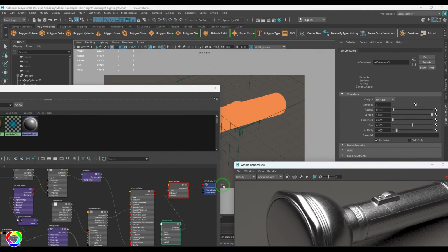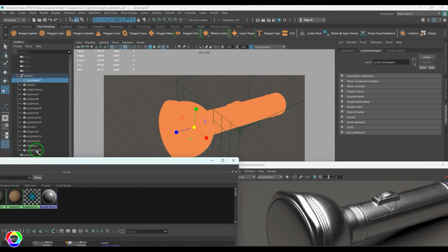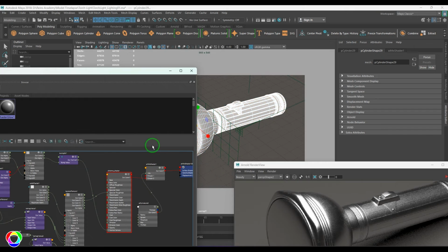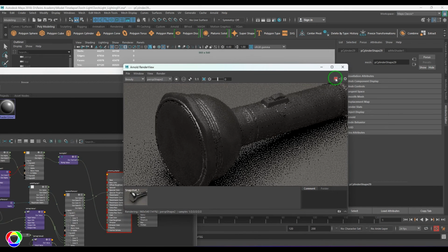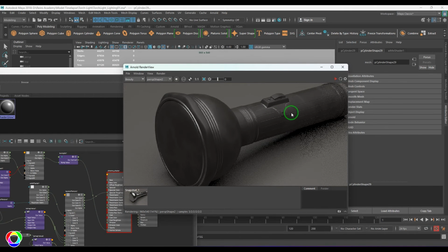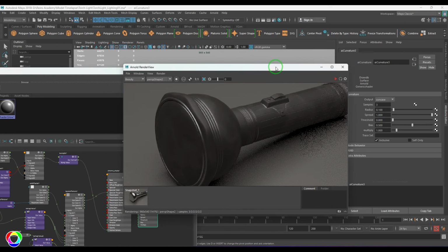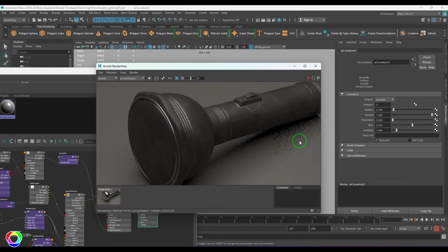I need to assign the mix shader. So I need to select all that objects and assign material to viewport selection and then render it. I should be able to see that dirt all over the model. So I'm going to select the curvature. Okay, this texture should be reversed. Let me try the convex also. That brings up on the edges, concave in the cavities. Okay, I can increase the radius to 0.25. I get a wider texture, but whatever is happening only reverse.